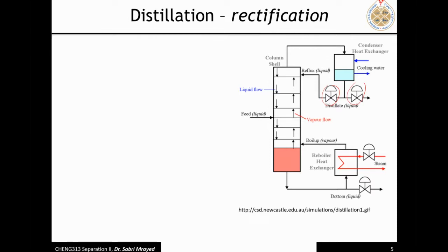But I want you to know there are three, let's call it, equipment minimum. The first one is called the distillation column, the equipment that carries the trays here. And we have the condenser that will be used to remove heat, cooling. As you can see, there's vapor going up. We need to condense some of that vapor, and then instead of having all the vapor as a product, we will use part of this product to return it back.